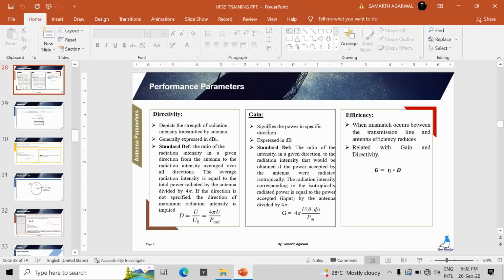Okay, so it is giving a maximum directivity in all directions. It will have an equal amount divided by an equal amount, whatever the x by x, it will be equal only, so it will come as 1. Now if I change this numerical value of 1 to dB, log 1 will be 0. It means it is neither producing power, neither emitting the signal nor absorbing, no plus or minus gain, nothing is there. Either plus 3 dB means it is amplifying, or minus 3 dB means it is absorbing, so nothing is there, but that is not possible.